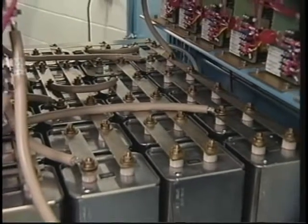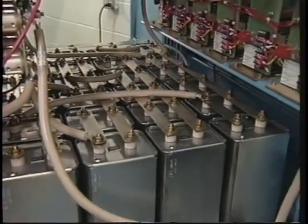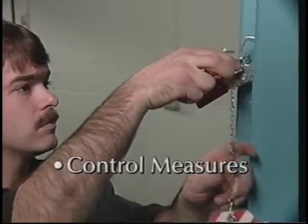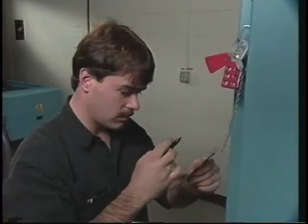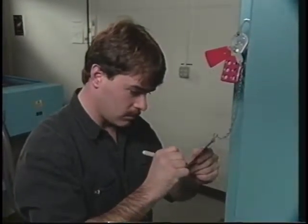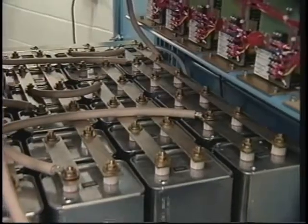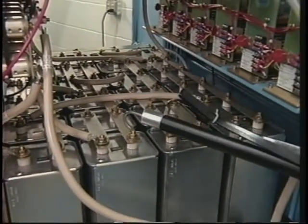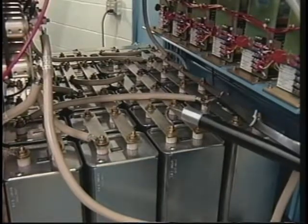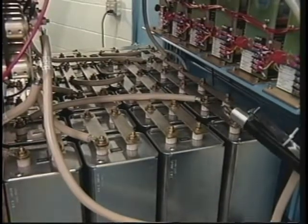Work with high-voltage systems produces the potential hazard of electrical shock or electrocution. To avert this potential, you should always follow good work practices. When electrical power is not required for maintenance or service, it should be shut off by following proper lockout-tagout procedures. For maintenance or servicing, capacitors must be safely discharged and grounded after the power is off to prevent accidental contact with stored energy.